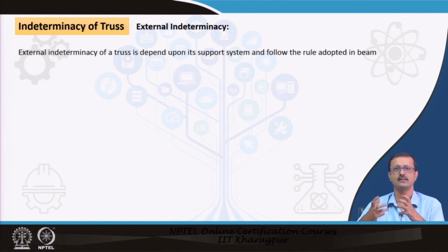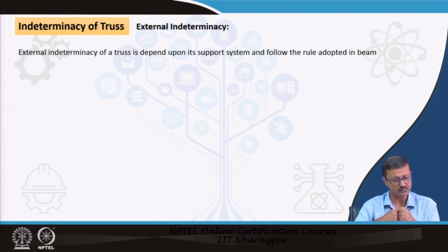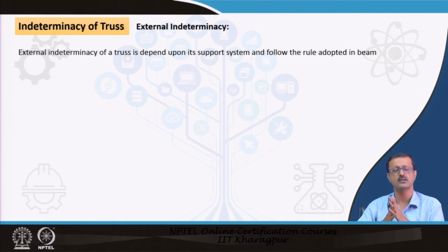The external indeterminacy of the truss depends upon the support conditions, that is, how many supports and what type of supports are there in the particular truss, because supports are an external body or external system which is plugged into a particular system.